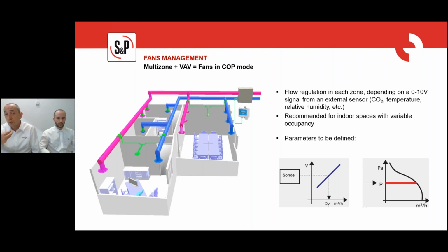And then it is possible to unbalance the other fans with a percentage of the speed of the fan which has the regulation. But it is important to say that it is not possible to have COP control mode in supply and extract at the same time. In CAD Compact Advanced, we have to decide which is the right one.